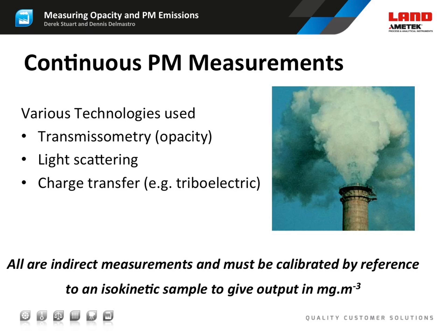The most common PM sensors employ some form of light scattering. Forward, side, and back scattering are all used. No matter which sensing technique is used, the sensor does not generally measure PM concentration directly, but it measures a parameter related to that concentration.